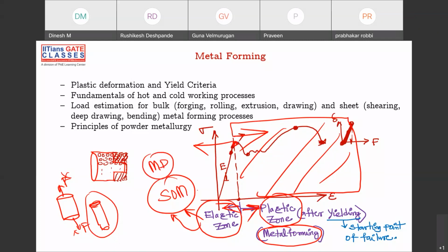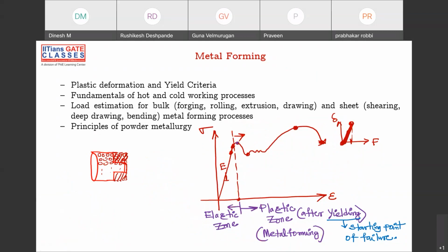You don't want the material to fail, right? You design things in such a way that your material is not crossing the yielding. You don't want the yielding to happen in any case. Am I right or wrong? And you'll also try to find out when this yielding is happening and you will give some factor of safety, and say that I will apply this much stress only rather than using this much stress. So you'll use some theories of failure and try to identify how it is failing, and then you'll use some factor of safety, and say, I want to be in a safer zone, so I'll give a certain amount of factor of safety. And once you feel that the load is beyond that limit, then you say that it is going to fail, and I don't want to use that force at all.